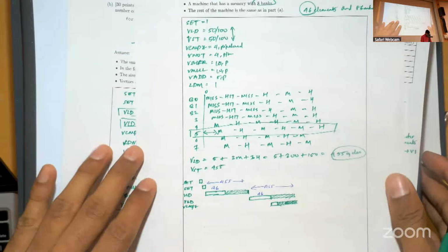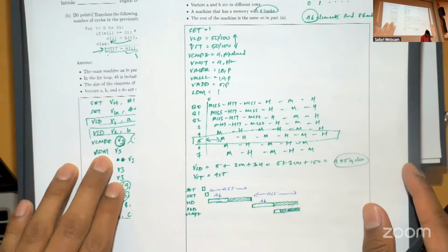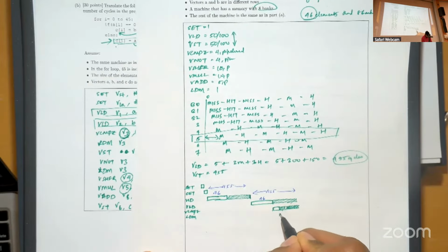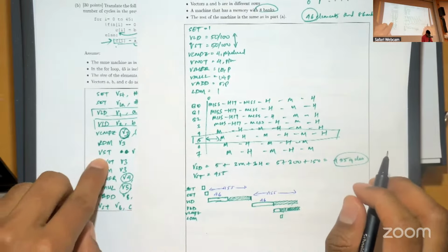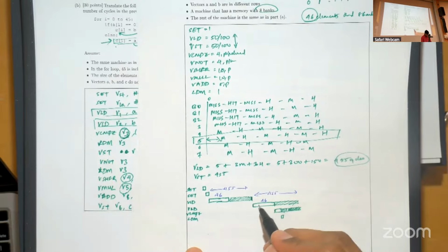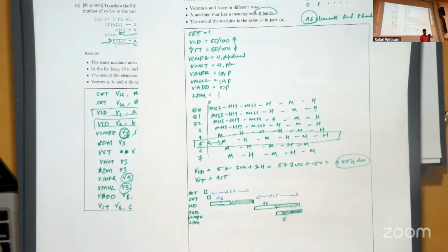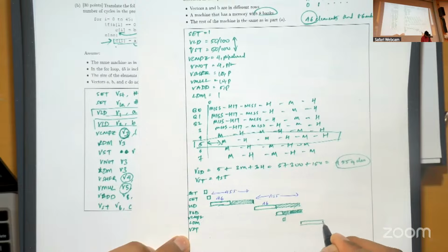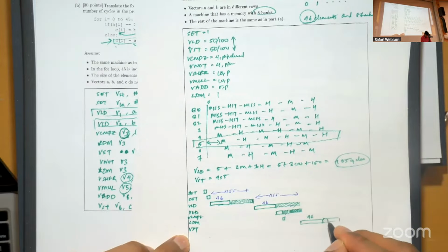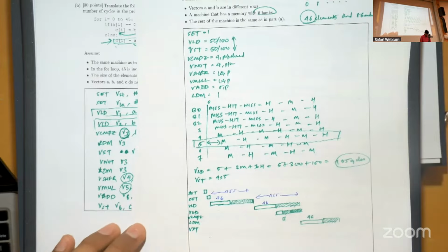Anyway, after vCompare 0, you have the load M, and load M takes 1 cycle. So load M is also nicely hidden behind the memory access latency. Next, you have the vStore. Now, unfortunately, the vStore cannot go ahead until the load M has completed because the DRAM banks are under usage. So the vStore starts somewhere here. Again, you have 46 cycles, and it's going to take some more time beyond that before you can issue other instructions.